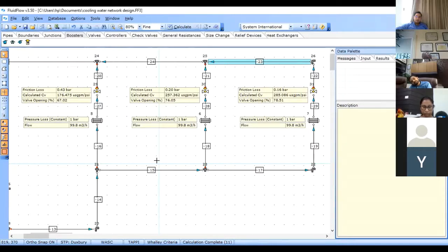So that time we'll end up providing more water. So on the process side also, the temperature will be on the lower side, which may not be accepted, right? So for that, if you have the flow control valve, then it will work fine. But yes, it is expensive. That we cannot avoid, right? So we need to actually check.